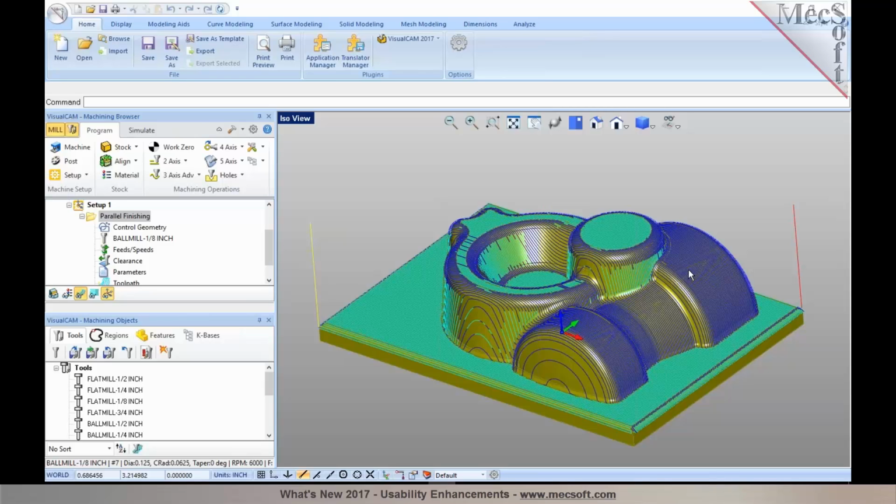So you have the option to set it globally and program your toolpath. So if you have a limitation on what your controller can handle for the maximum arc radius, you can specify it right in there.